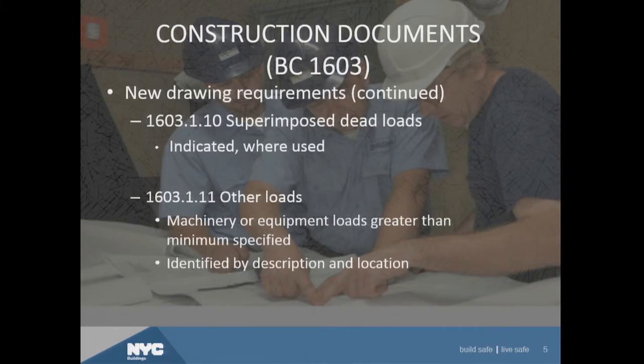A little more on some new structural design provisions that were added by our committee, and these are primarily committee enhancements. Superimposed dead loads. When a structural design incorporates the use of superimposed dead loads as part of the design, then those superimposed dead loads have to be indicated on the construction documents as part of the 2014 code. There are no superimposed dead loads specifically called out in the code, so that's not something that's being done. But if the superimposed dead loads are used as part of the design, then they need to be indicated on